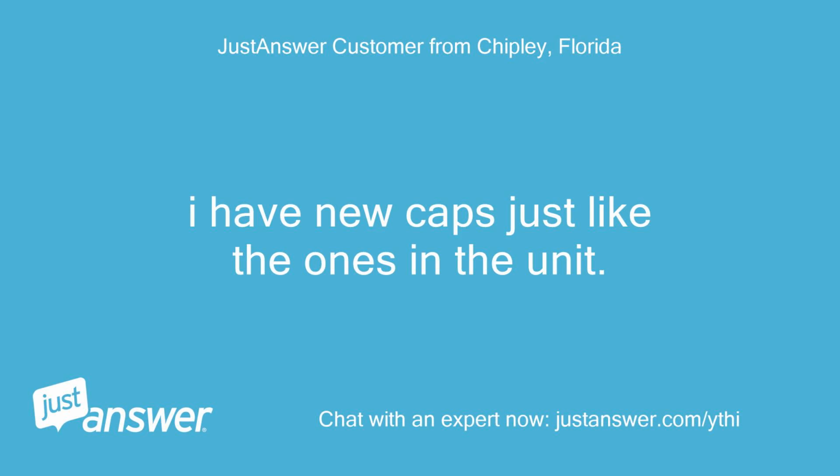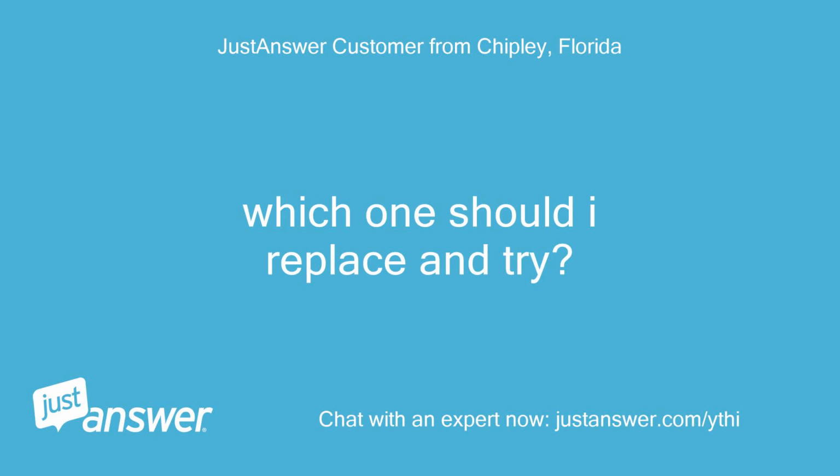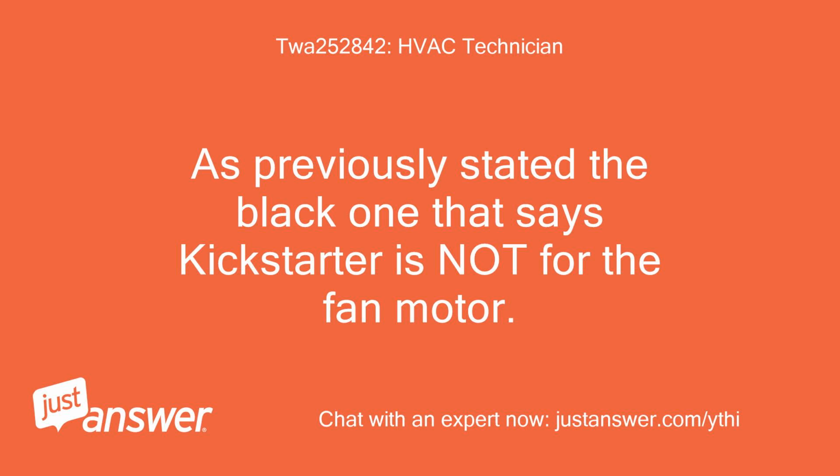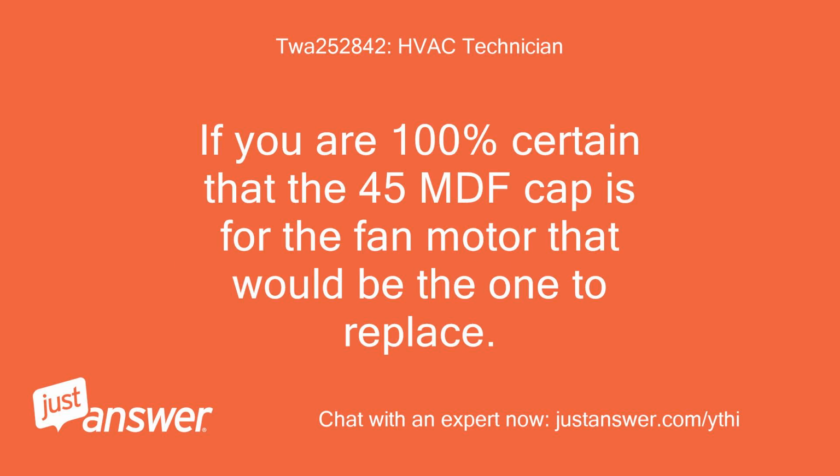I have new caps just like the ones in the unit. Which one should I replace and try? As previously stated, the black one that says Kickstarter is not for the fan motor. If you are 100% certain that the 45 MFD cap is for the fan motor, that would be the one to replace.